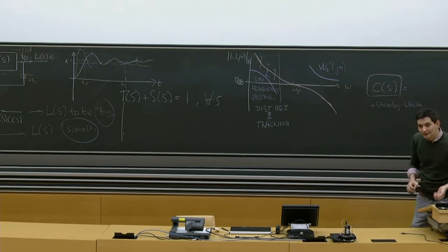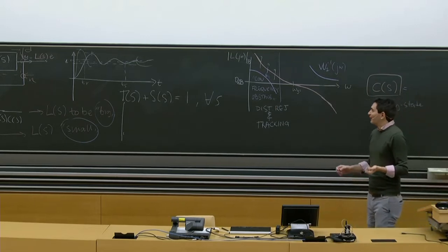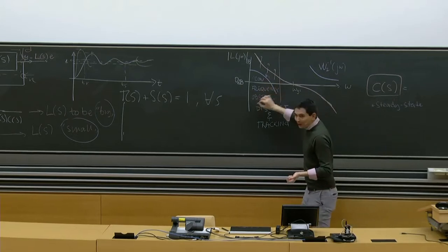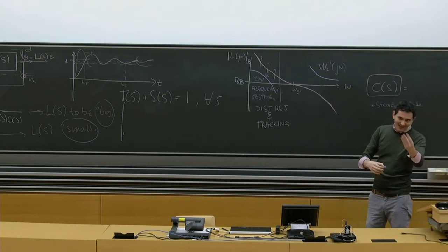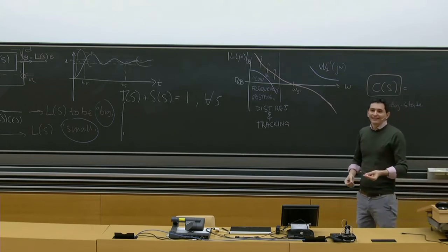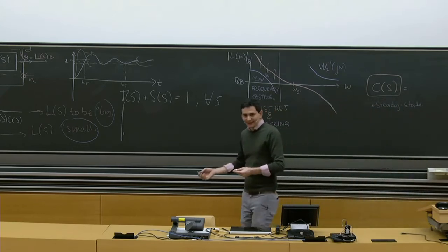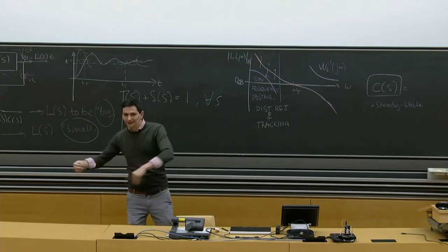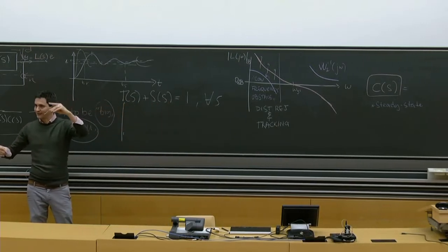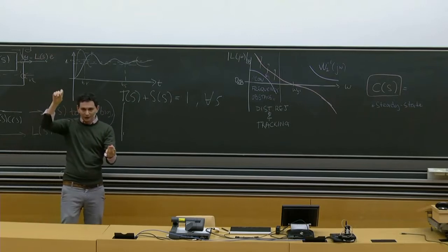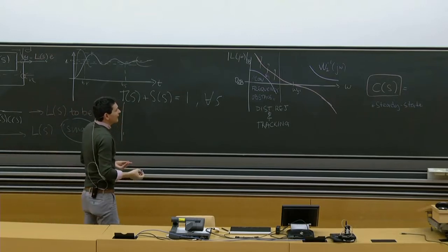Integrators, exactly. So this is the low part of the frequency spectrum, right? If you go very, very low, which is as frequency equals 0, that's what the steady state is. The steady state in time, time infinite, corresponds to zero frequency. And we saw that by seeing that a constant input was an exponential with zero frequency, basically, right?